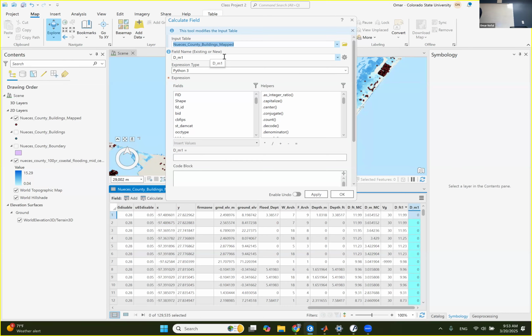And I need this code to repeat the same process for every building, right? So basically you need a for loop that goes: if this building is archetype 1, pick the fragility for archetype 1, read the flood depth of this building, go into the fragility, and do some interpolation to get the probability of damage. Once you are done, go to the next building and do the same process until you finish all the buildings, and then end. That's basically all the damage analysis code is doing, right?